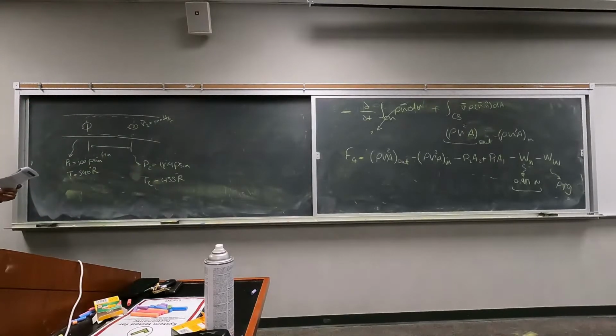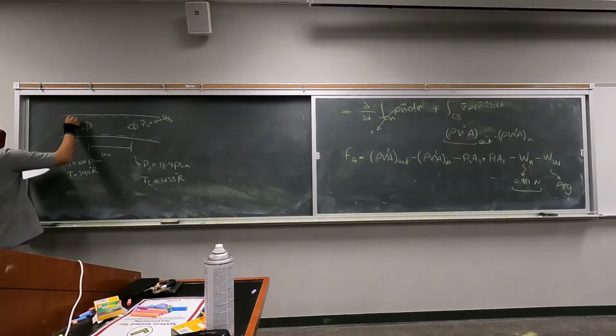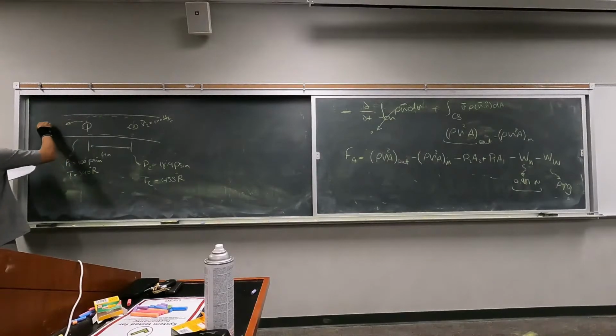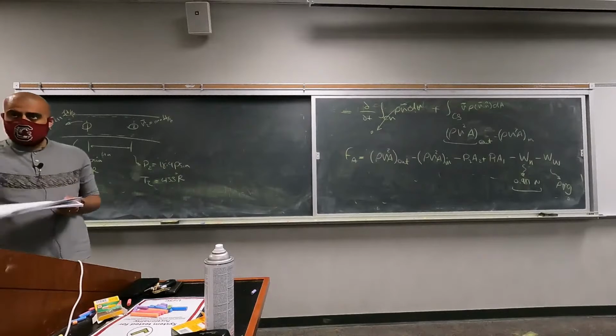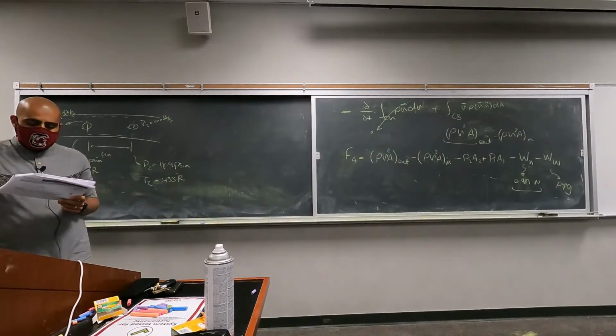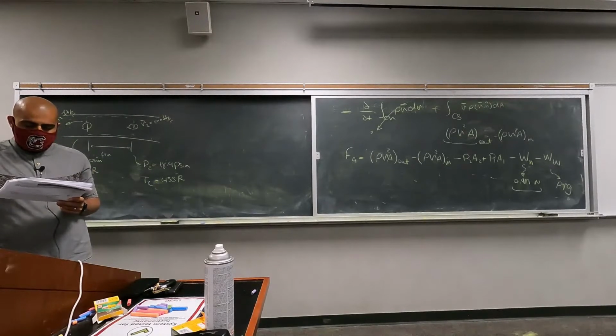And we find an example: the average air velocity here at section 1. We actually have solved this example before for the conservation of mass. It is 219 feet per second. We want to assume uniform velocity distribution at sections 1 and 2. We want to determine the frictional force exerted by the airflow on the pipe wall, between sections 1 and 2.